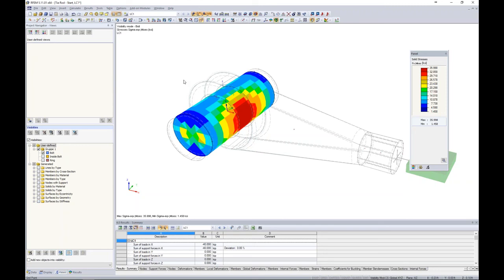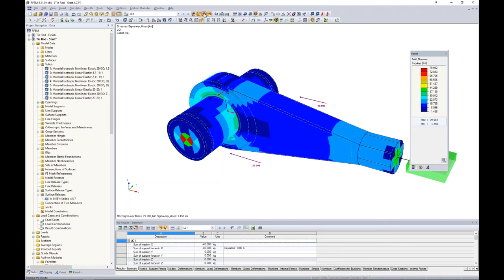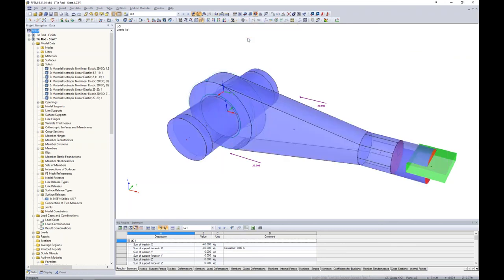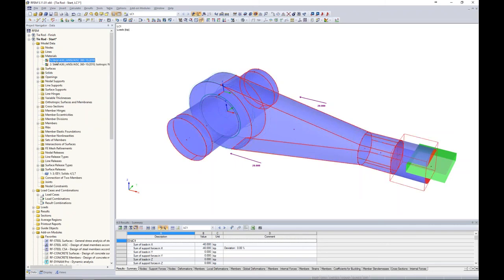And one last thing to cover is that you'll notice here that my solid stresses are not exceeding 36 KSI. Well, that would be pretty good luck, but the reason why is because I'm utilizing nonlinear materials within the program. So jumping back to my data tab, let me turn off my results and take a look at the rendered view. And my materials are listed here of what I'm using within the particular model.